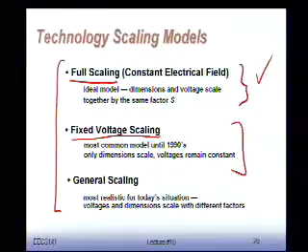They did a whole bunch of tricks to keep that 5 volt as a constant, till they basically couldn't stick to it any longer. Because the fact was that power dissipation, as we'll show you, it's nice when you keep supply voltages high. You might imagine, remember our analysis of propagation delay? Look at propagation delay, we see that higher voltages typically go faster. If you keep your voltages higher, you're going to go faster. So, hey, you get a lot of good performance.